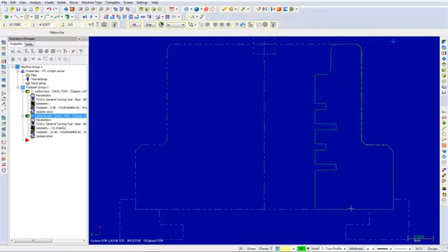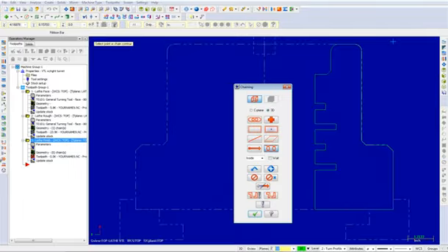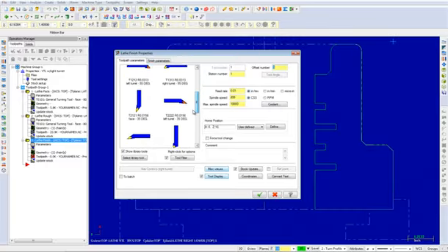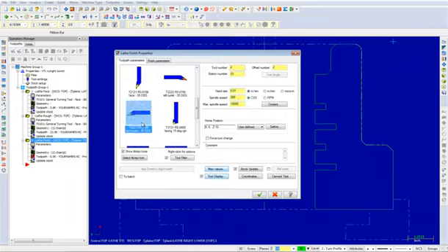We will now use a finished toolpath to finish the part. Choose the Finish icon. When the chaining dialog box appears, pick the Last button. Now select the OK button to exit the chaining dialog box. This time we will select a right turret 35-degree tool from the tool list. Input the comment as shown.